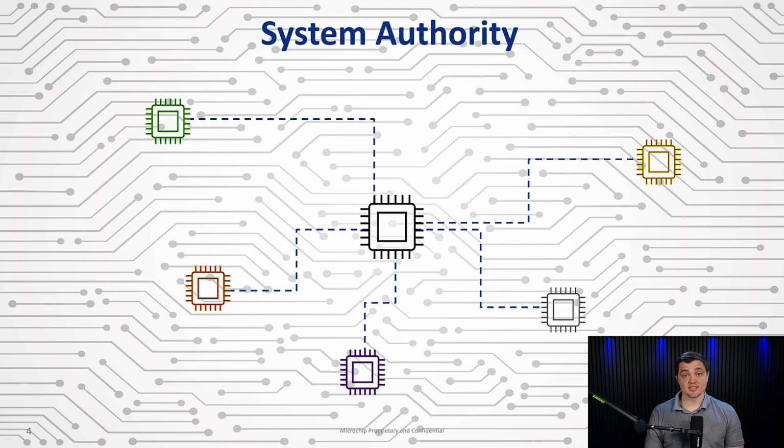Once we've measured this device fingerprint, we can use it to derive a private key that will be unique to the device that's utilizing the PUF technology. Again, the culmination of all the micro variations of the transistors across an entire device can't be replicated by even an identical device, so the key that we generate will be unfalsifiable. And the beauty of it is we don't have to store it anywhere, so it's in no danger of being extracted from the device somehow. We can simply derive the key when it's needed, and then it's gone once it's done.